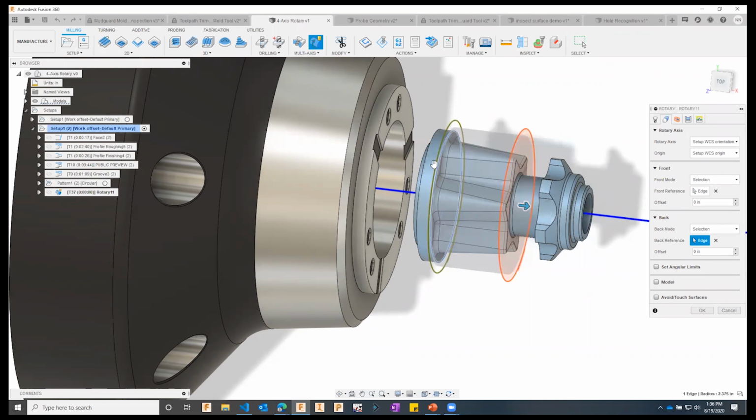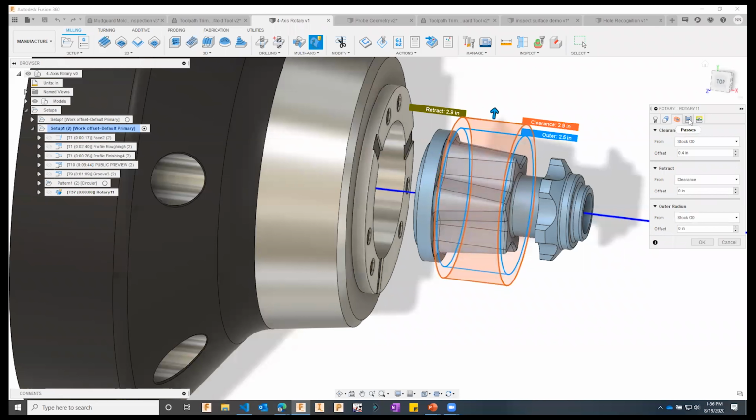I don't want that tool to come all the way up onto the outside edge, so I'm going to offset that by my tool's radius, which is a 1/4 inch. I could have also said tool underscore diameter divided by 2 to get that straight off the tool. And you'll see it, it'll populate when I hit OK.